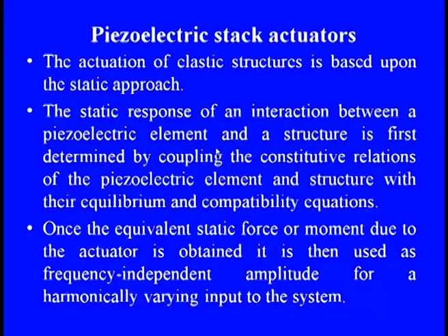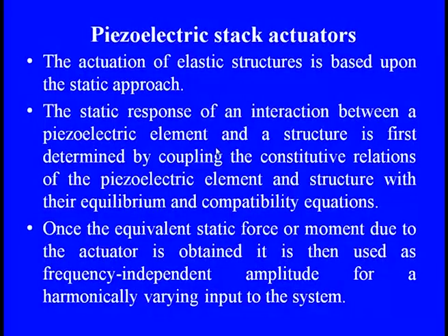So, when we use these piezoelectric features in sensors and actuators, we need to see what the actuation feature is in the elastic structure, because when we apply a static or dynamic approach, we need to see how these actions are being taken. If you are talking about the static response, then the interaction between the piezoelectric element and the structure has to be determined first, and then coupled with the constitutive relations of the piezoelectric element and the structure, with their equilibrium and compatibility equations. Because it cannot be abruptly applied wherever actuations or sensing features are there, if we want the accuracy of the result.